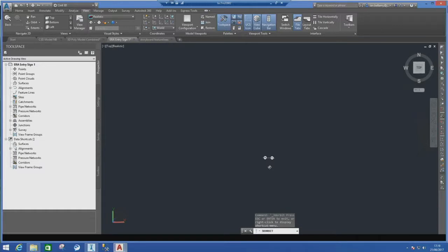The issue we have with this is when it brings them in, when they're in place, it creates an FBX. An FBX file doesn't support coordinate systems, so when they come in, they're all distorted and you can't actually read what they say. So what we have to do is, as the designer is placing them, he places them in the location, copies them to another file, places them at 0, 0, with 0 height, 0 x and y, 0 rotation. Takes the schedule that we create for the signs and takes the x, y, z and the rotation of each sign and just places them in a table.